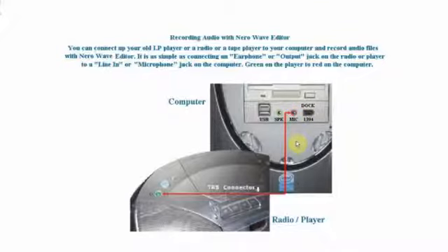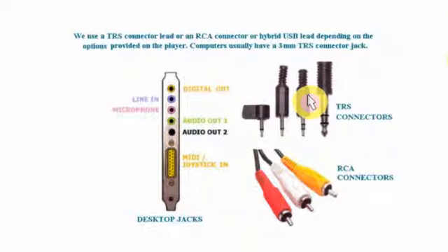We will use a 3.5mm TRS lead, which utilises the most common connectors. Some output devices provide only RCA jacks, so a hybrid lead may be needed. Headsets sometimes use a USB connector, so this will have to be recognised when checking device settings on the computer.